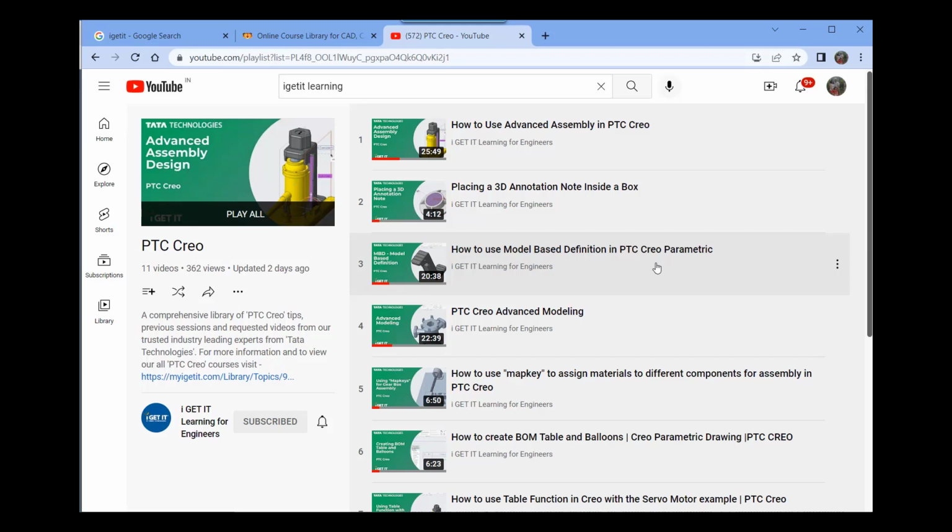And then further inside those CAD native models, either Creo or CATIA or anything, that 3D annotation information was being sent to lightweight files, and those lightweight files were being visualized by the manufacturing people on the shop floor. So this is a kind of getting rid of paper, and everything regarding the drawing information, all the annotations, were present on the lightweight 3D model on the screen of computers only. So that was basically the concept of MBD or 3D annotation.